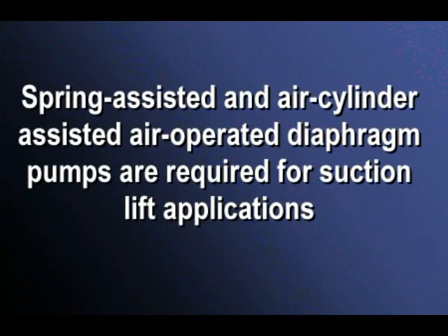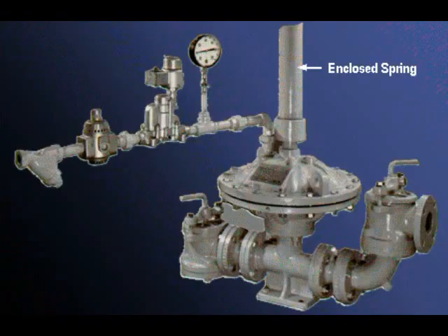If suction lift is required, a pump variation where the diaphragm is mechanically assisted must be used. We will examine spring-assisted and air cylinder-assisted diaphragm pumps. In this variation, the diaphragm is mechanically lifted by a spring-activated rod during the fill stroke. This action draws fluid into the pump.